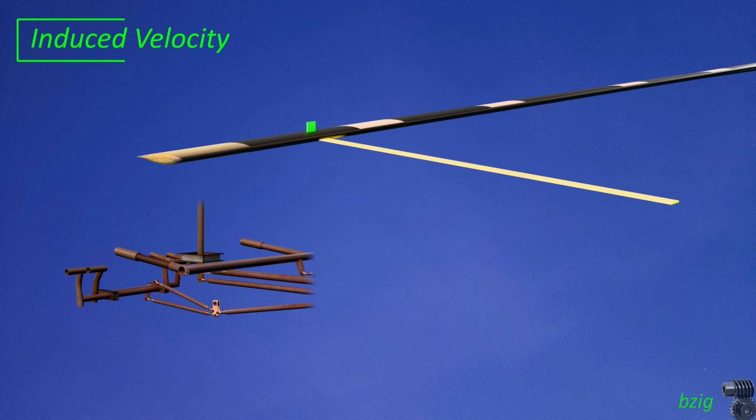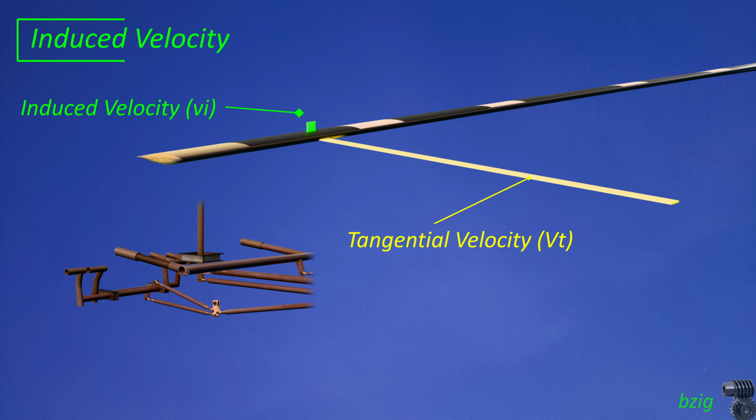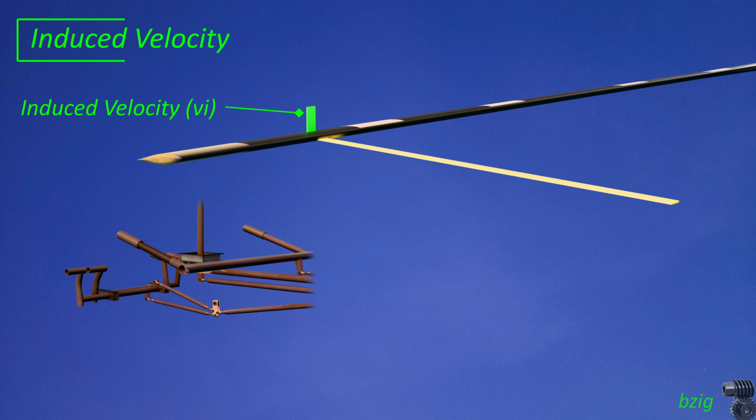I use those same equations to drive the induced velocity vector you see on the screen. This vector changes as I raise and lower the collective lever, and intuitively this makes sense. We know that downwash is low when a helicopter is on the ground at flat pitch, and it increases as the pilot pulls up on the collective. The calculated induced velocity is almost the end state of this analysis.